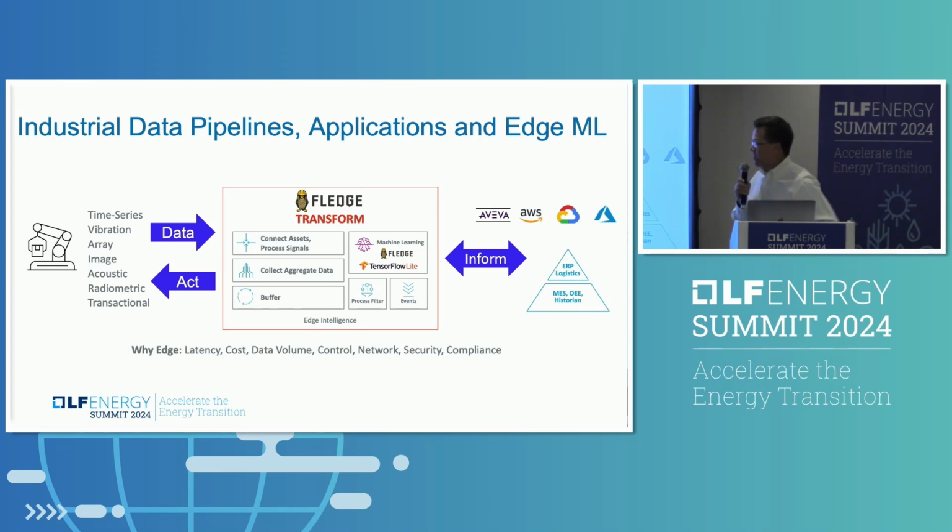But at a super, super high level, what FledgePOWER can do is collect data from any type of data, any protocol, any data map, and then once you ingress that data, you can filter it when you receive it. One of the easiest things to think about is, let's say, an accelerometer or a PMU. I want to do signal processing right when I receive this raw vibration data. So it can begin to transform that data right when you get it, and then it converts it to a common JSON, and from that common JSON, it converts it again into the protocol of the destination.